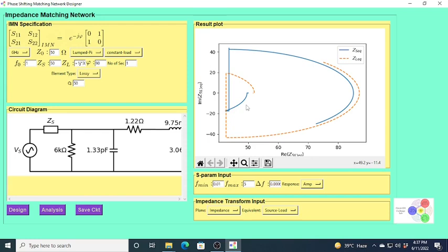Okay, the insertion loss is basically 1 divided by S21, so that is more than 0 dB. Okay. So, you can see here that it is not perfectly matched from the graph itself, because to be perfectly matched, the source equivalent at the load point should ideally be 75 minus j30, but here it is showing 72.7 plus j30. So, this additional thing can only be compensated through additional transformation, through additional compensation. Okay.